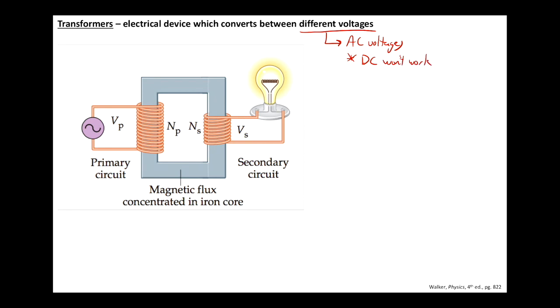Although we could say something like a DC pulse can cause a brief effect. If you think of a DC pulse, that's like, turn on some current, turn it off. Well, that's a change in current, which causes change in magnetic field, change in magnetic flux, and you could get something to happen, but it's just for an instant. If I have alternating current and therefore alternating voltages, this is something that's just going to keep operating because the magnetic flux is ever changing, never stops changing.